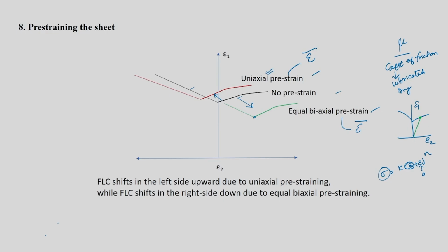For one particular case you will reach a forming limit. If you change the lubrication, let us say lubrication is better, then you may get a higher limit strain, a better epsilon 1 star and epsilon 2 star value as compared to the previous one, but it will reach the same forming limit.